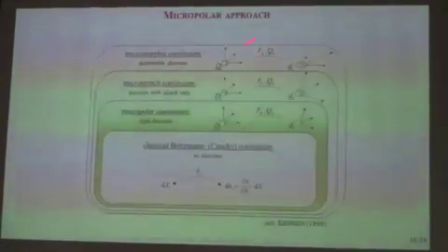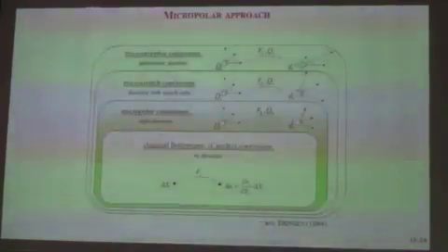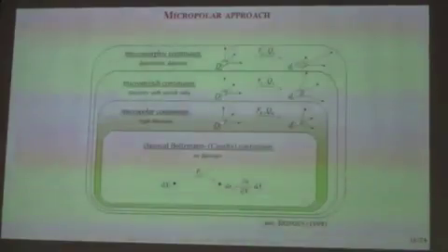Therein we need a deformation gradient to deform a line element from reference to actual configuration, and we need some tensor to build up the different directors, how they are changed. They can change angle and they can rotate, and this will build up the micromorphic continuum.